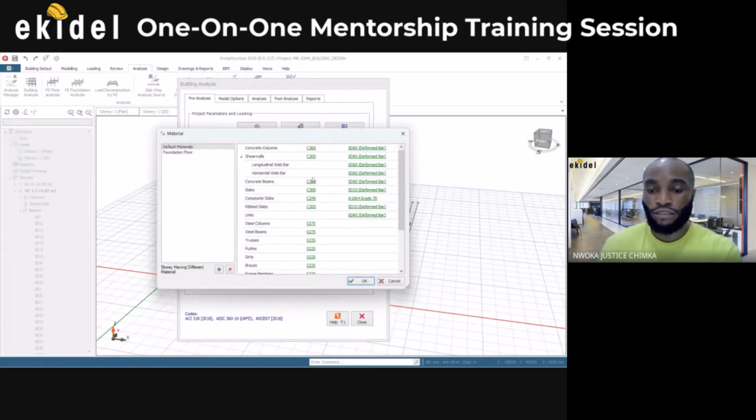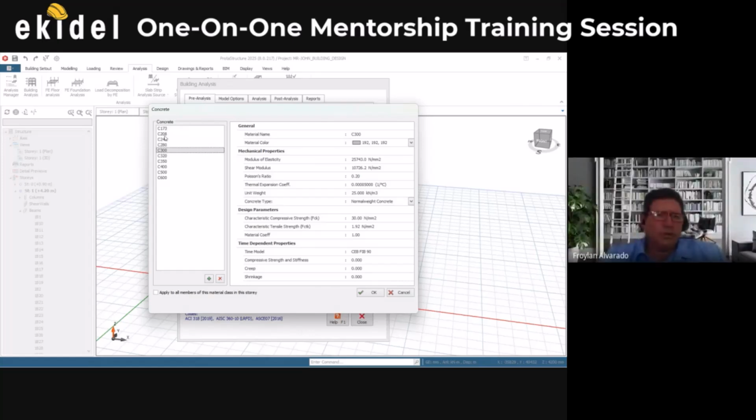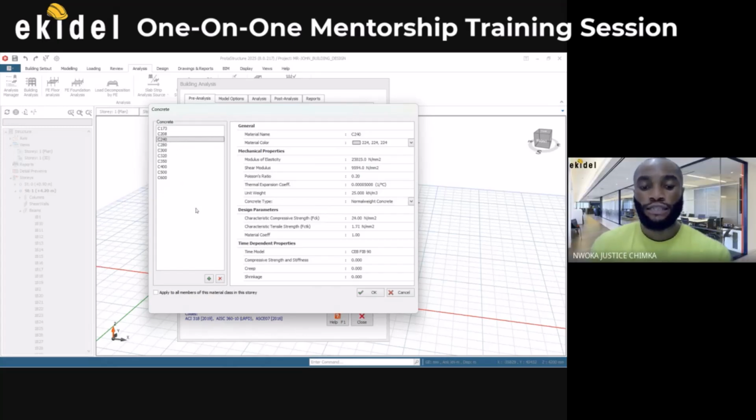Now this is our concrete grade and these are the rebar or steel grades. I'll click on this one here, which is the concrete grade. Now you need to choose your grade of concrete. What do you guys use in your country? 240, that's fine, 240. Then you can choose to apply to all members, that's to beam and column, all members. Then click OK.